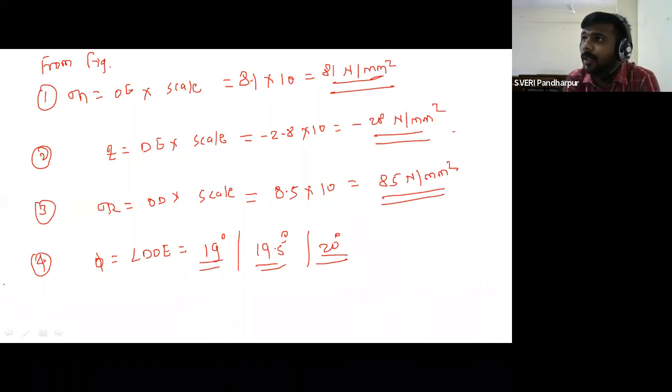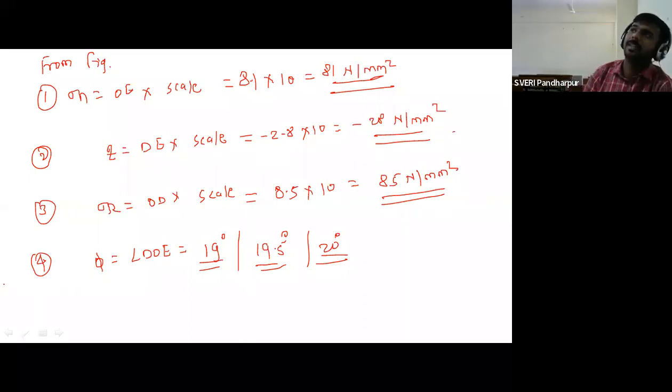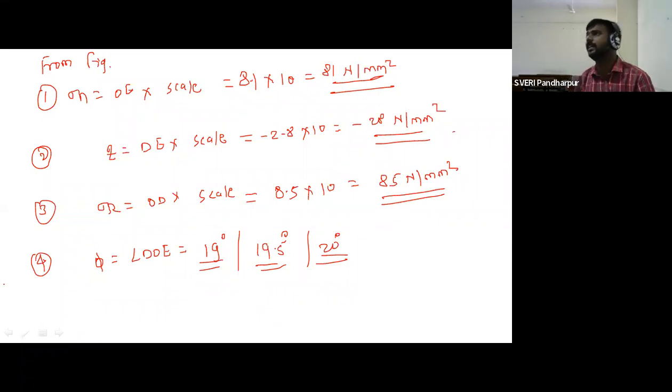Okay, so this is about case number 3. Have you understood the procedure? Have you got the difference? Once again, I want to tell you, for case number 2, sigma x and sigma y are there, and the procedure is very simple. I think as compared to case number 3, case number 2 is simple because we are taking the reference point C as the center of AB, and by selecting that radius only we are drawing the circle. And point A will be the reference point to represent the 2 theta angle.